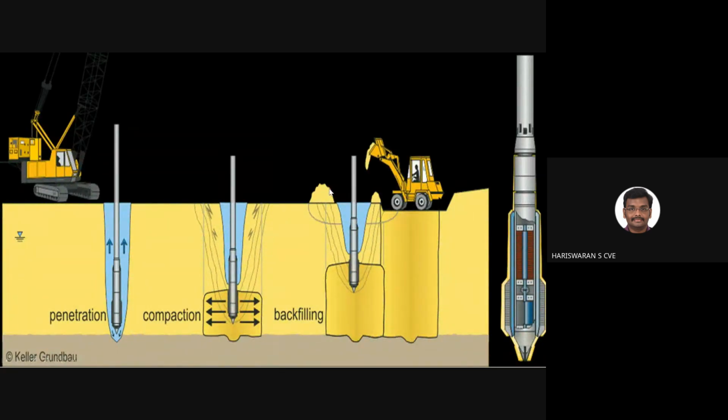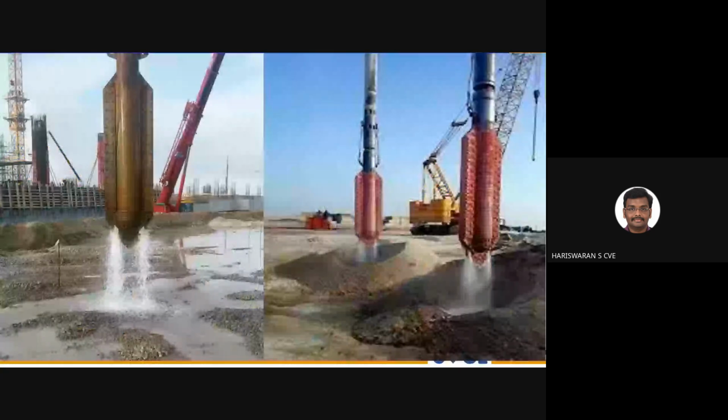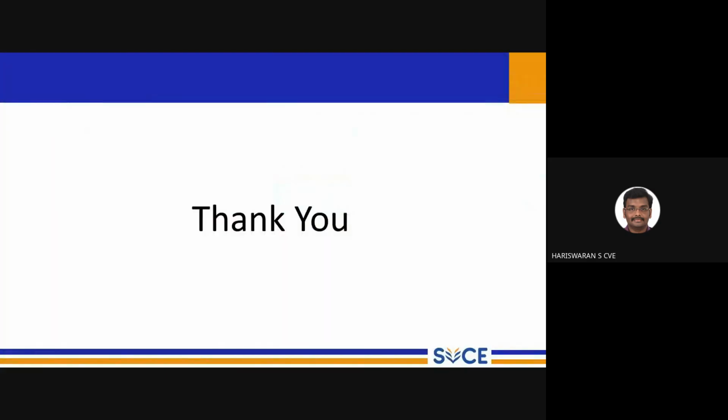Now that may be filled with any other naturally available material, like sand or stone. Whatever the construction we are executing, usually we call it a sand column or stone column. So that is the end product of this. By constructing n number of sand columns or stone columns in and around the region, the whole region is going to get stabilized. Then above that we can plan for construction of any type of structure. So that is the main outcome of these different techniques of ground improvement.